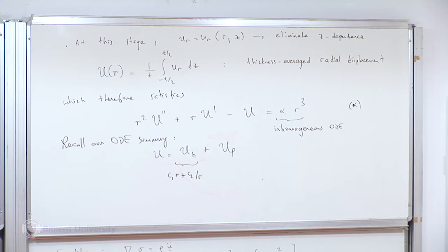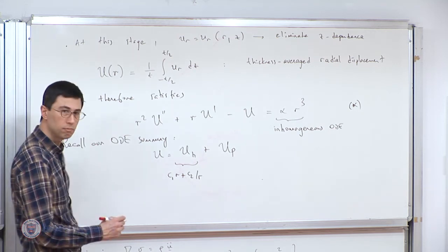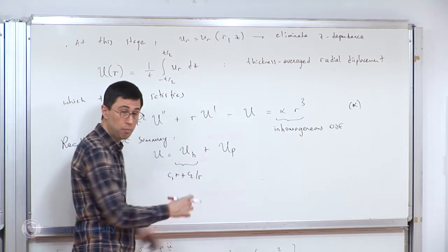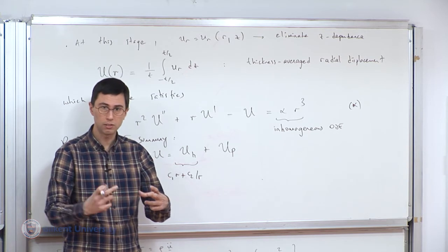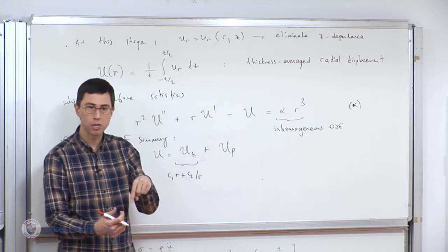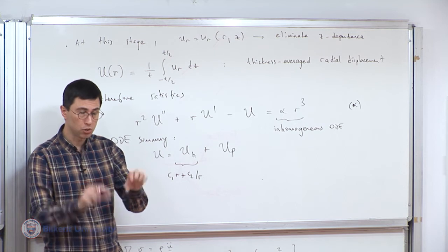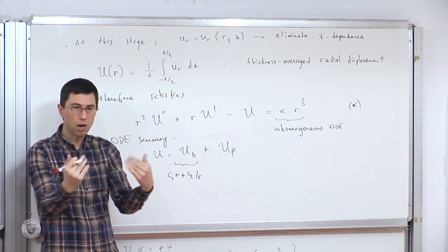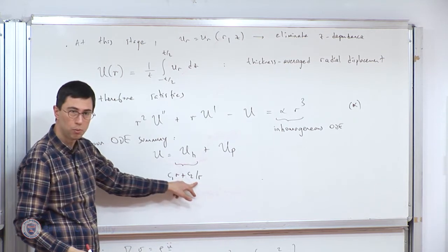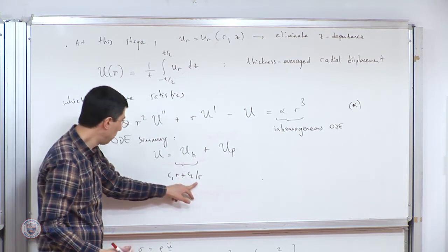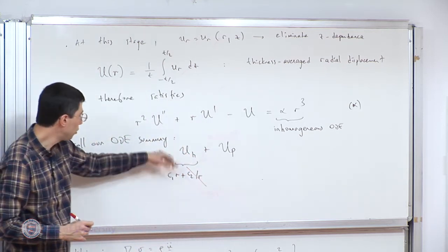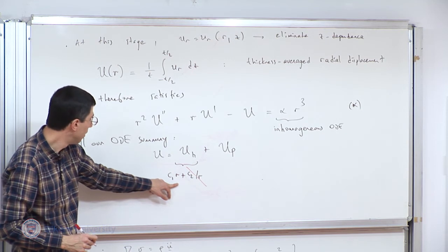We'll solve it several times. And moreover, I know that r in my problem can go to 0 because it's a disk that is solid and spinning. It has no empty portion in the middle. If it did have an empty portion, like an annular disk, then r does not go to 0, so this term could be retained. But presently it can go to 0, so I omit that term. So the homogeneous solution has only one constant.